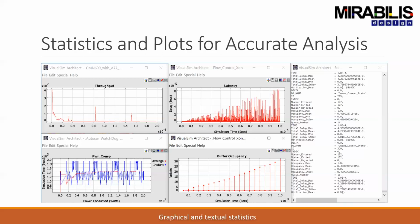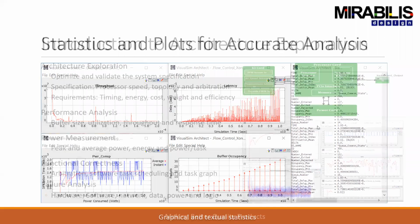So obviously you do have a design issue, either from a scheduler standpoint or the size of the requests coming in from some of the masters, that is causing a pretty large buildup of buffering without increasing the throughput you're getting from the system. Other secondary statistics give you your delay stats for min-max, mean, and standard deviation, plus how many entered, how many were rejected, and how many actually exited successfully.